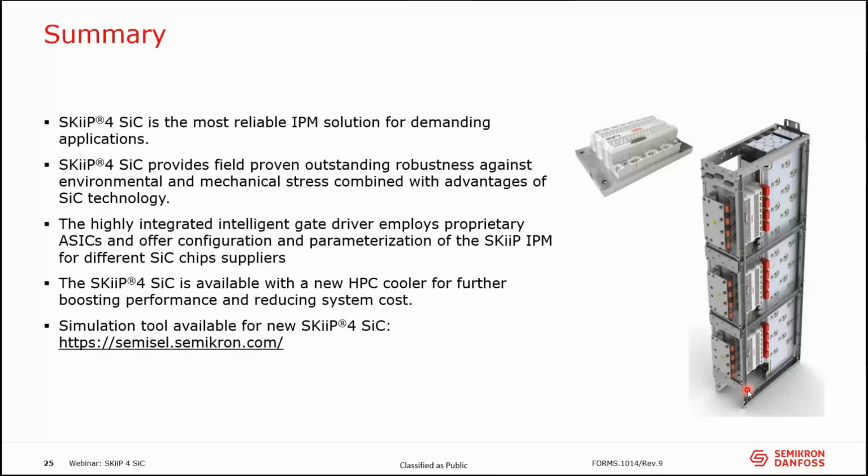In general, the housing of the SKiiP is not 100% robust against moisture. But the technology that we have inside prevents corrosion, prevents the failure because of this humidity problem. But anyhow, we still have that climate class, I guess 3K. So condensation is not allowed for the application. Right, not hermetically sealed, but it's still resistant against humidity. Yes. I know there's quite a bit of tests going on about that, so it's very important here.